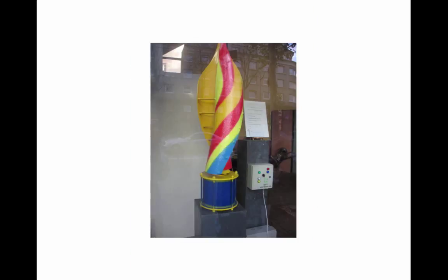This is another novel geometry wind turbine shape, very sculptural. So this one is horizontal axis. It spins around this way. And then there are wires and magnets down here. And you can put this on top of a tall pole. And again, it's beautiful, but it produces very little energy. It's got a very small amount of area exposed to the wind, and that's kind of your collection area. And a lot of these novel geometry wind turbines, especially if they're placed low to the ground,